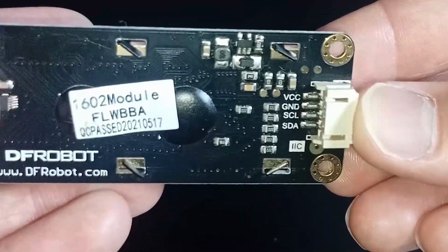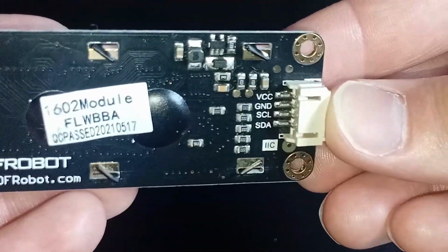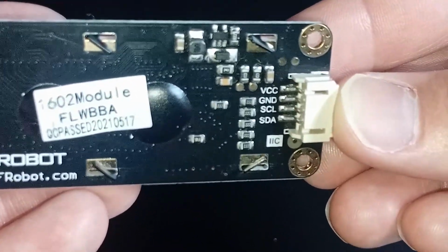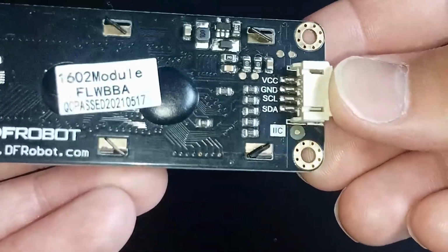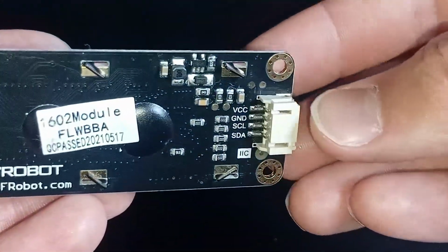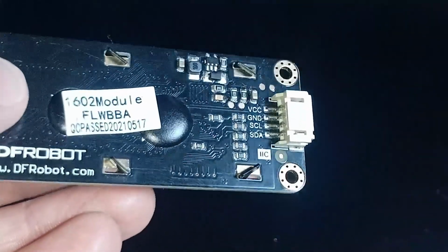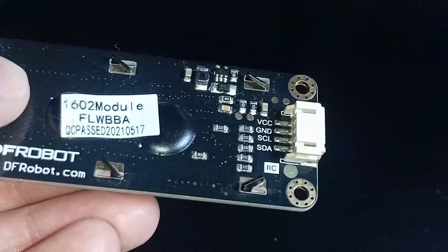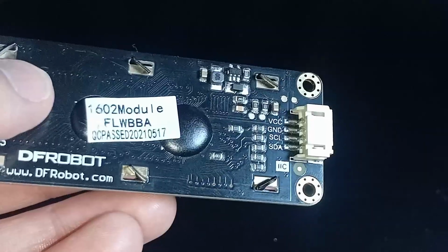One of the biggest advantages of I2C is that it allows multiple devices to share the same 2 wires. That means you can connect several sensors, displays, and modules to the same SDA and SCL lines, as long as each device has a unique address. This is extremely powerful, especially for beginner projects, because it keeps wiring simple and clean.